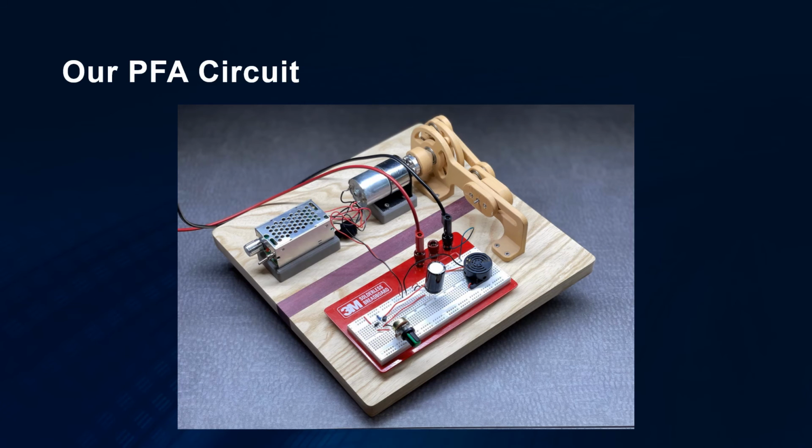Here on this breadboard in the forefront is the circuit we built. Right here, this potentiometer is what we used in place of R1 so that we could test different resistances, and that was kind of fun to play with as we determined the actual ohms that'll work best for this circuit, which was around 500 to 750.